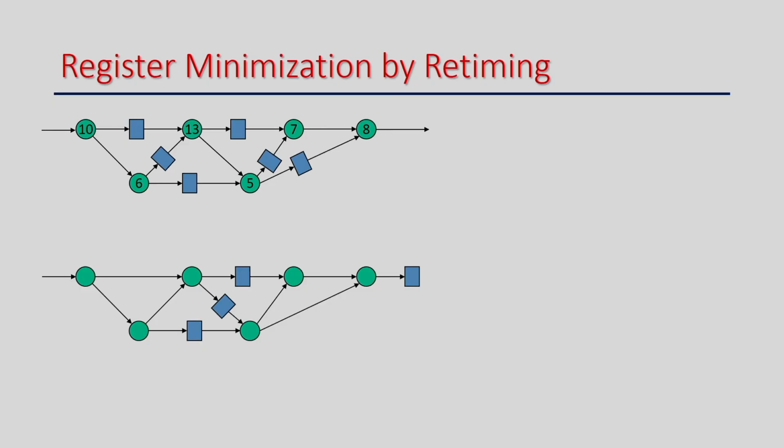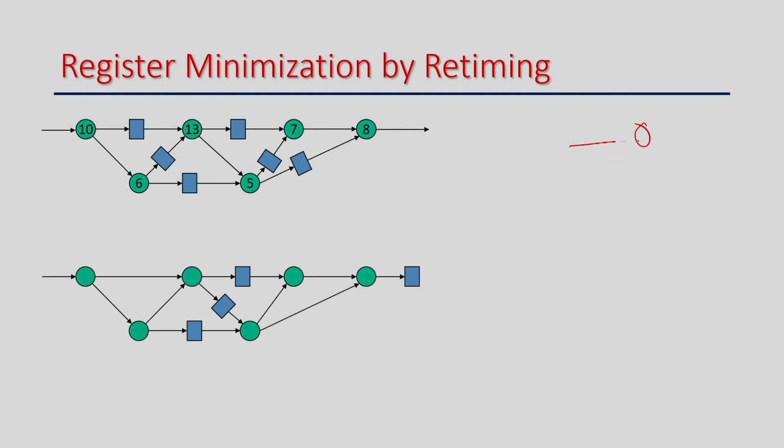The basic rule is that, suppose there is a high fan-out, and there are 3 registers here. The latency of the circuit is 1, because from the input to the output side, all paths have 1 register, right. Whereas if I just move it to the input side, this is a correct one, because all output fan-outs have registers.